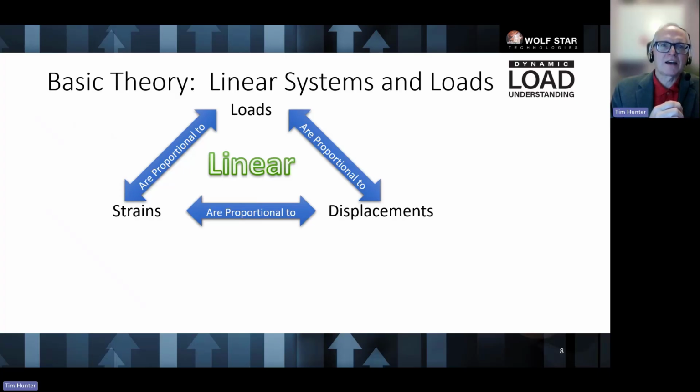We're going to stay away from nonlinear areas like welds, bolted joints, and areas of contact. We're going to be in nice nominal areas where the strain response remains linear and proportional to the exterior loading. The loading can be as nonlinear as anything. It could be sinusoidal, ramp loading, impact loading. That's okay. We just need to keep this proportionality between the strain response and the exterior loads.